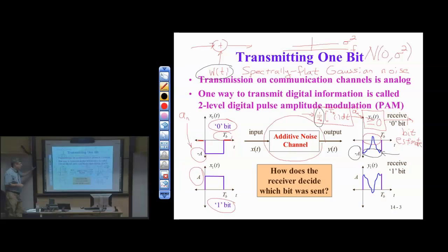Again, averaging this out helps us smooth out the noise, reduce the high frequency noise, and gives us a better estimate of A. Then all I'm going to do is take the average value. So I'm going to get an estimate very close to minus capital A. And in this case, all I really need to do is compare against 0. So my estimate can be fairly wrong in estimating minus capital A. I can be off by a lot and still get the detection right.